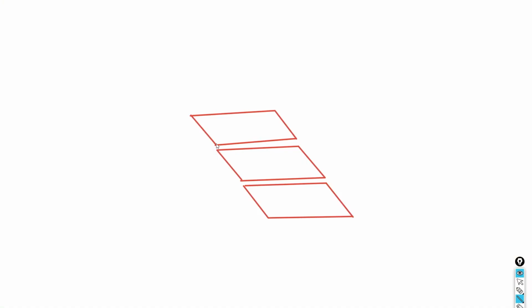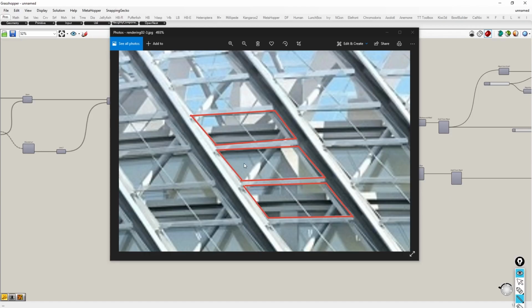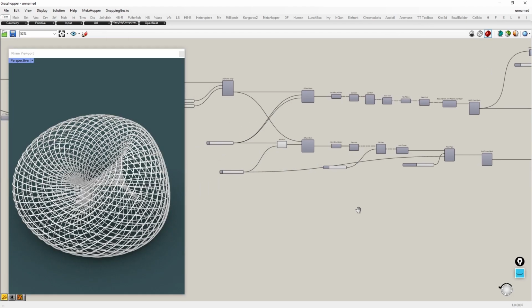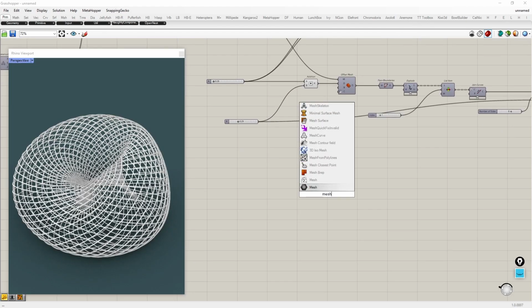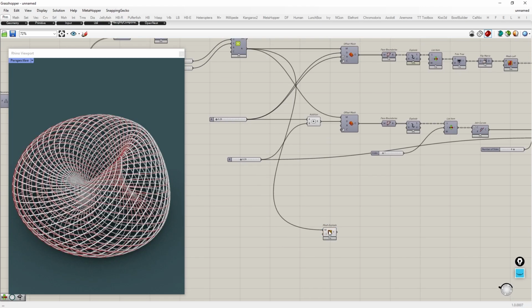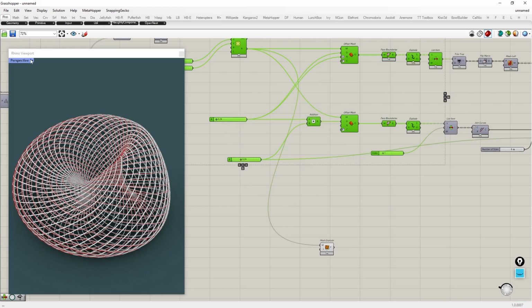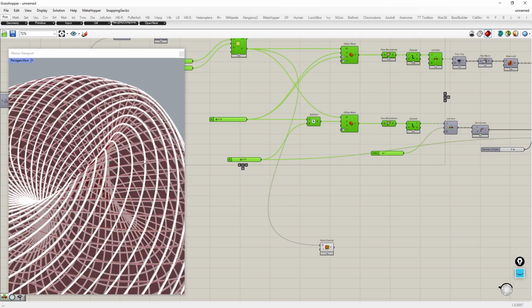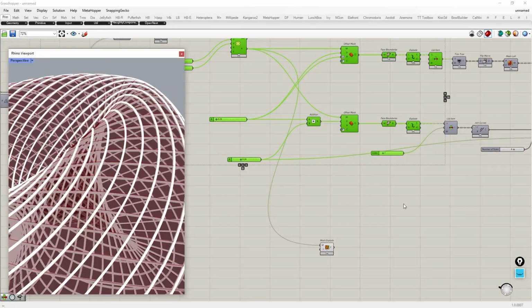Next, we're going ahead to make each panel. The panels are a little bit inclined, so we make parameters that control the inclination. Explode the mesh so we can get each face separately. Next, rotate each panel on one of the edges as a rotational axis. By extracting one edge from each face, we can get a rotational axis.